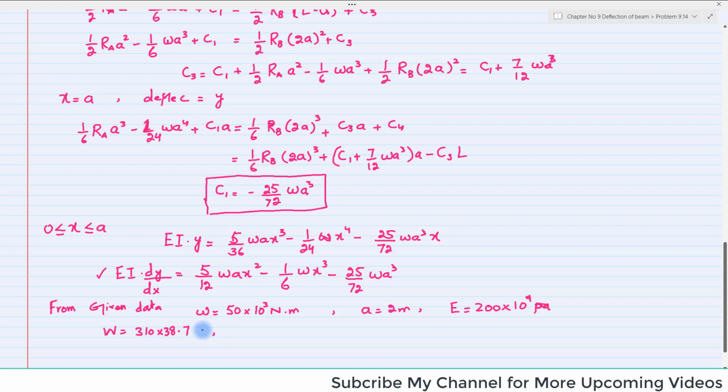So you have to go to appendix 4 of this book, which is available at the end, and you can find I equal to 85.1 into 10 raised to power 6 millimeter to the fourth, or you have to convert it into meter, so 85.1 into 10 raised to power minus 6 meter to the fourth.